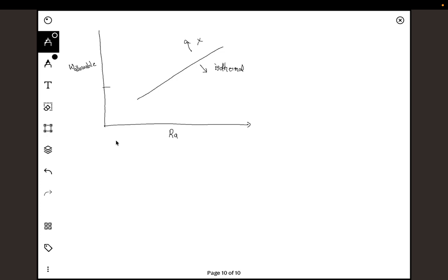So for a given wall thickness, as the Rayleigh number increases, which means I will be moving like this, all the points will be satisfying the isothermal wall assumption better and better beyond a point. So for turbulent natural convection, where the Rayleigh numbers are very high, we can assume the walls to be isothermal. Of course, if the wall is very thick, then you cannot.